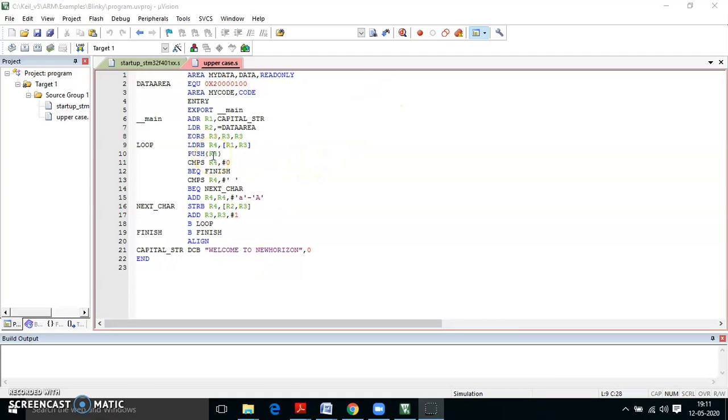Next we are going to load this data in the form of stack locations. Like we know, the push and pop registers are basically connected to the stack. So here we are utilizing the R4 register, and this R4 register acts like a temporary location pointer where the array of data is located, with R4 and also linked with R3.